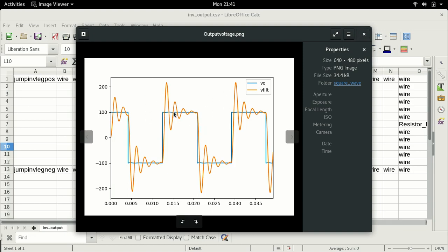But what's important here is this is completely useless. If we could not apply the blue voltage, which is the rectangular waveform, we cannot also apply this orange waveform. This orange waveform is almost useless. So what do we do? What this shows is that the low frequency harmonic content is so significant that we are not able to make hardly any change to the harmonic spectrum.